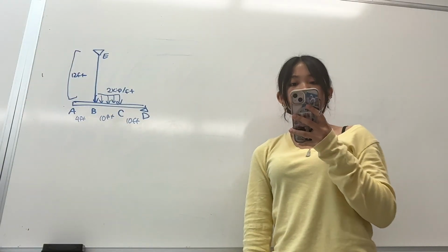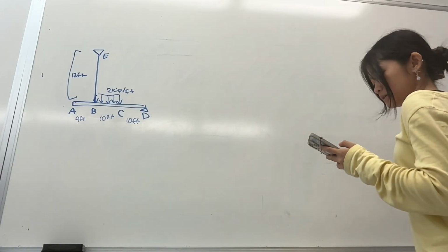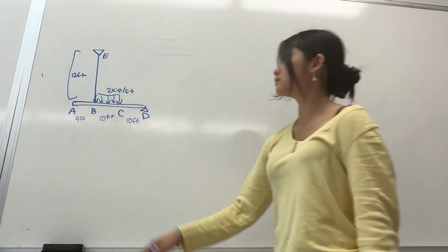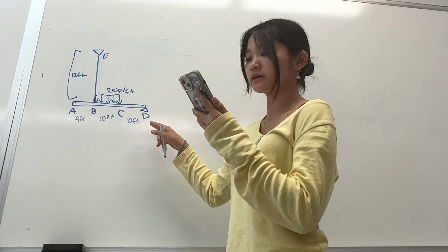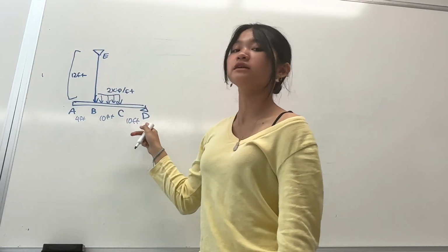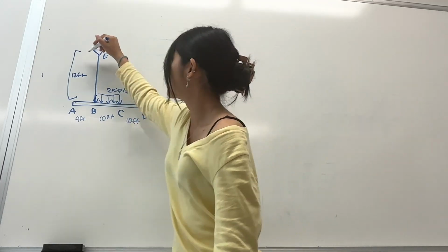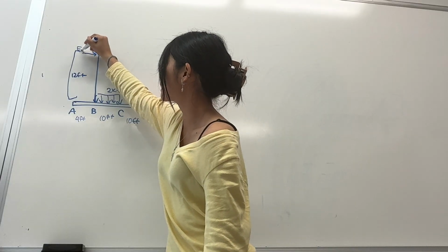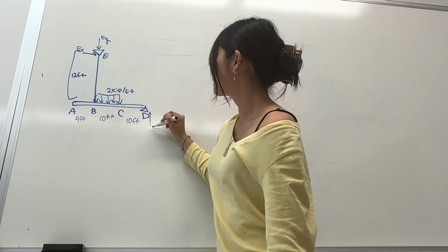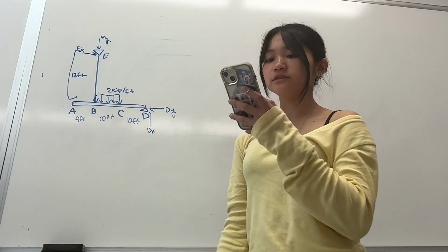Yeah. So, I think I'm supposed to work out the whole problem. So, no problem. We can draw our forces on our free body diagram here. Because this is a pin right here and right here, we can add our X and Y forces. So we have EX and then EY, and then we have DX and then DY. So those are our 2 forces.